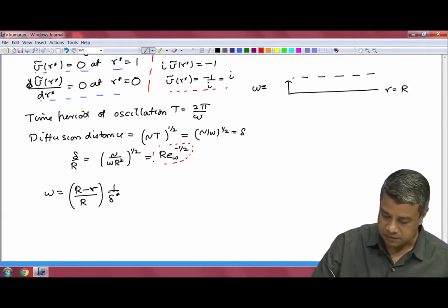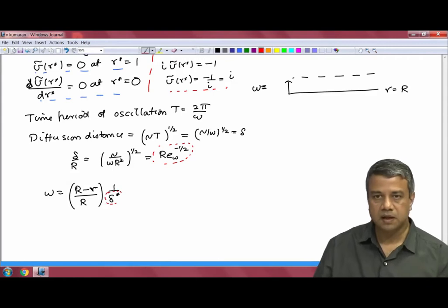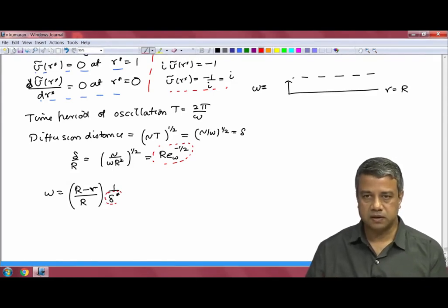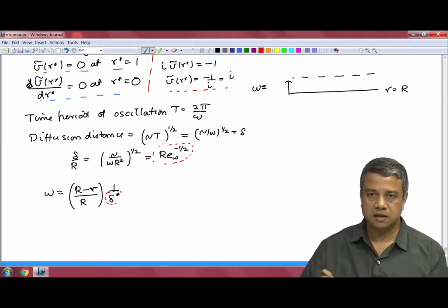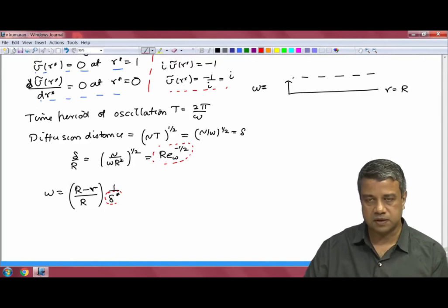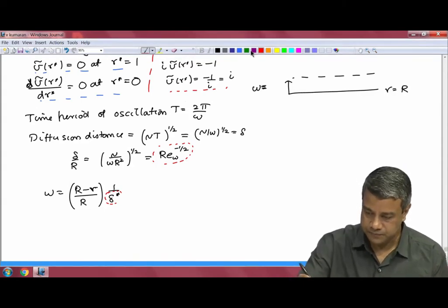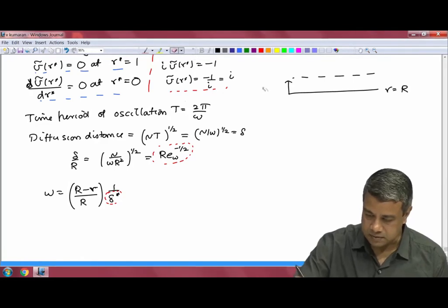I am dividing it by a small number here in order to expand this out, so that within this region diffusion and convection are comparable. The pressure gradient, the time derivative and diffusion are comparable. So, this is what I will call my scaled distance from the wall.